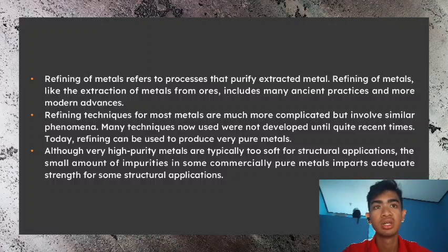For this reason, commercially pure titanium can have advantages over other metals in the design of heat exchangers. It offers good strength, resistance to erosion and erosion corrosion, a very thin conductive outside surface film, and a hard, smooth surface that limits adhesion of foreign material and promotes dropwise condensation.